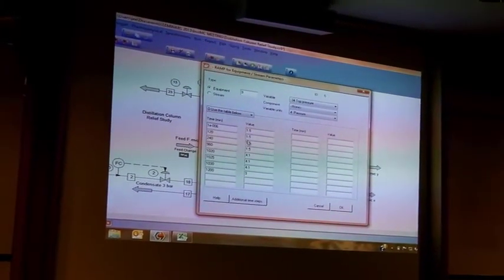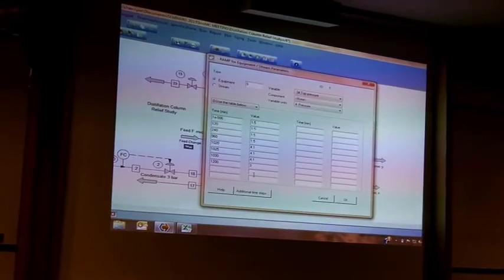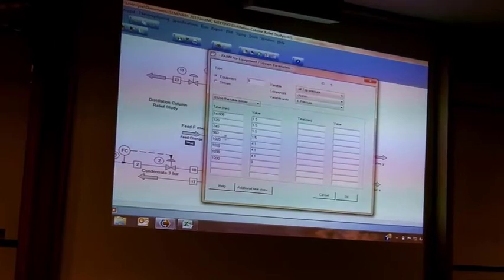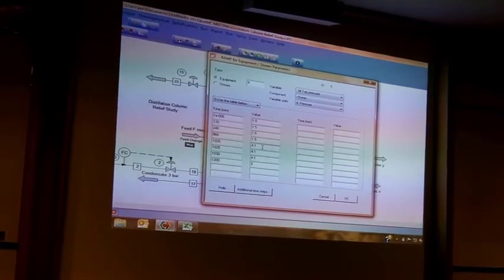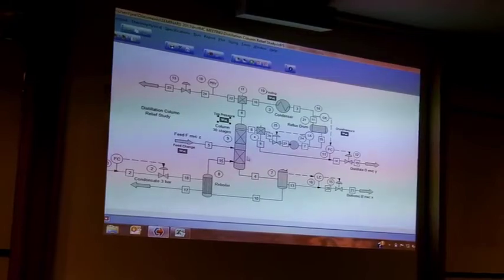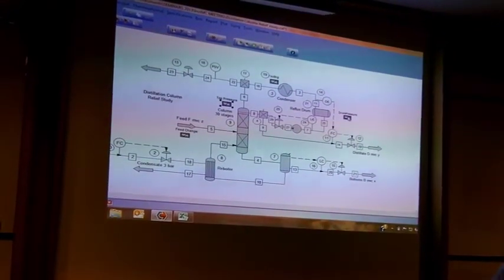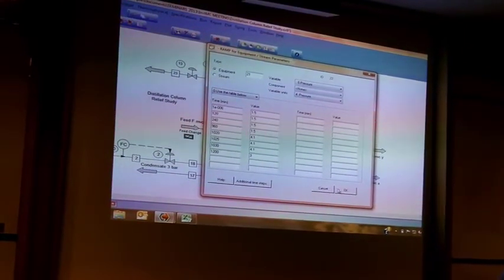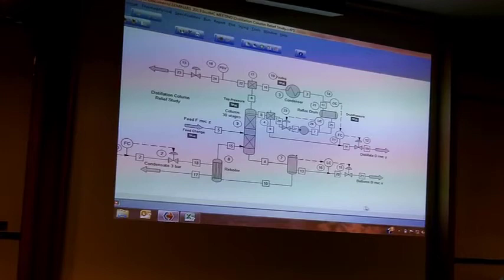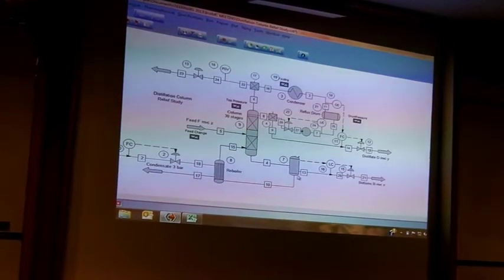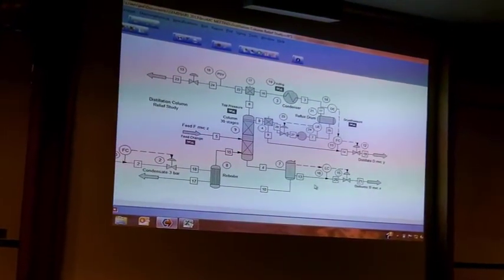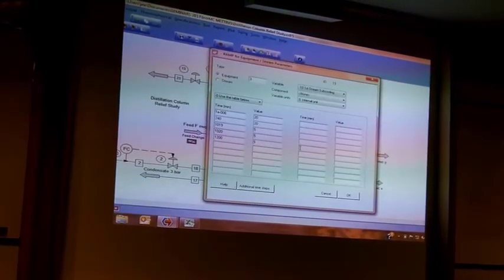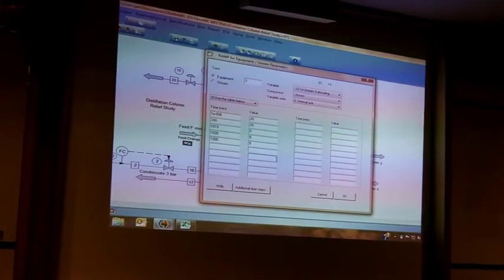But we can set these ramps on individual things. So that's me changing the pressure on the column. At 960 it's 1.5, and then it's ramping up to 4.1. But for the simulation to work, I've got to do the same thing in the reflux drum. That's the same as before, you've seen that. And I've just put this in. I'm actually introducing fouling here.